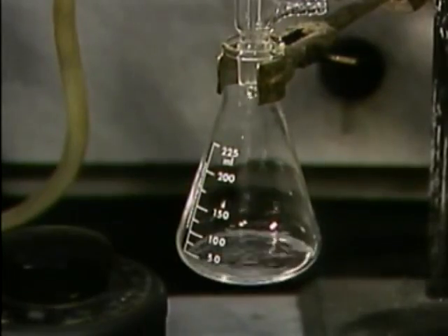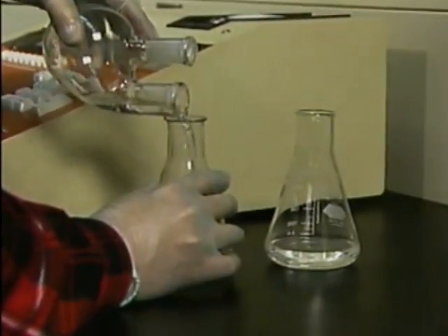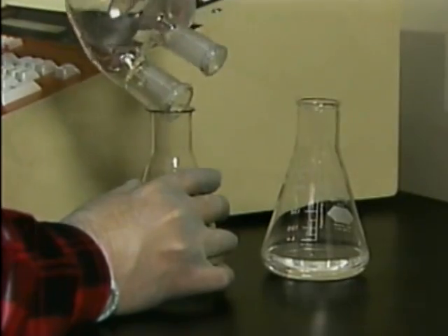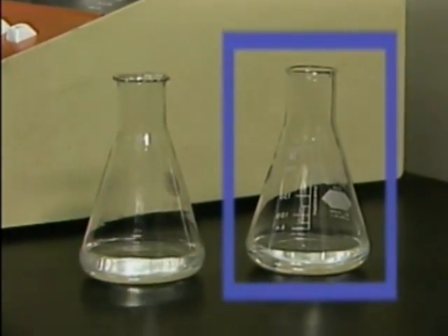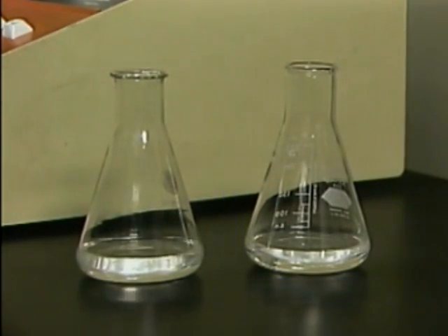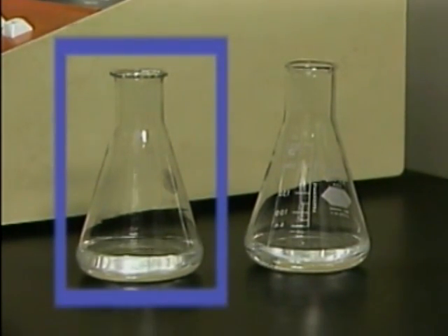As temperature increases and the mixture's initial boiling point is reached, the lighter component starts to boil and vaporize. But because the heavier component has some vapor pressure at this temperature, some of it also vaporizes. The vapors condense in the condenser, and liquid starts to collect in the receiver. When the distillation process is complete, we can analyze the contents of both the receiver and the container. The mixture in the receiver is primarily pentane, but there is some cyclohexane. The mixture in the container, on the other hand, is mostly cyclohexane with a small amount of pentane.